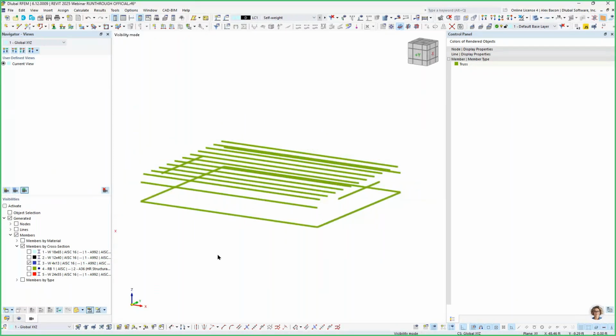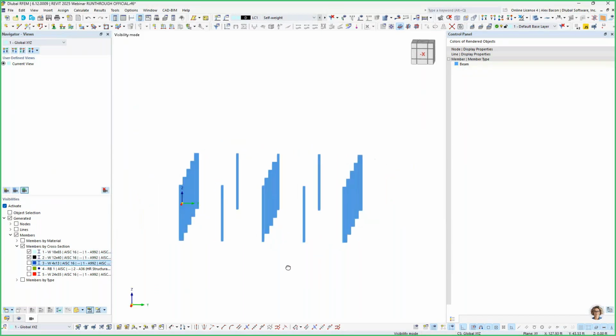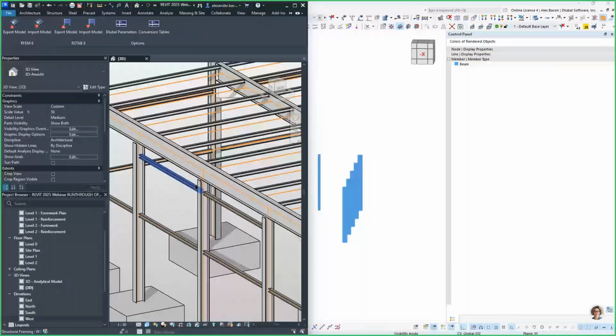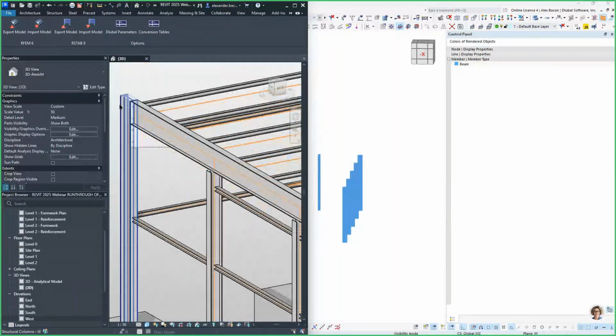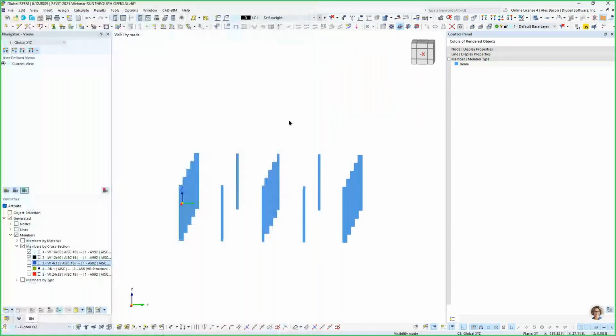And now lastly, I would also like to apply hinges to my wall and center columns. So I will create or show those. So yeah, I would only like to apply some member hinges since we have pin connections here at the top of my columns. I just realized I forgot to mention the connections. Yes, I have some connections defined in Revit. So for the columns and beams, I have some plates and fasteners, and then the columns framing into the beams here are pin connections. So I'd like to consider that in RFEM.